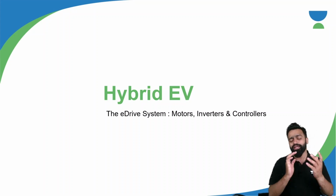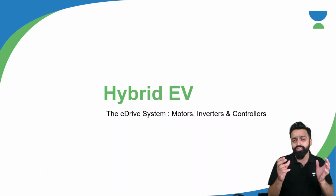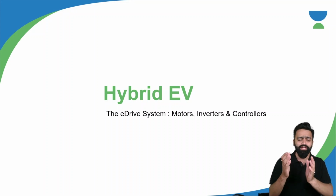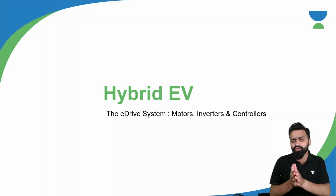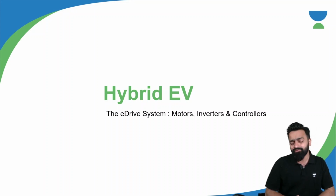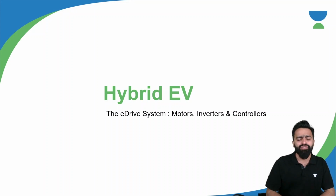I hope you are enjoying the lectures, and in the previous lecture we understood what types of motors are most used in the manufacturing of electric vehicles. We have also understood what is MCU, that is motor control unit, and what is VSI, that is voltage source inverter, which is used to convert DC into AC and reverse in case of regenerative braking. We also understood the different applications, advantages, and disadvantages of different types of motors. Now, this is the concluding lecture on the eDrive system, which consists of motors, inverters, and controllers.